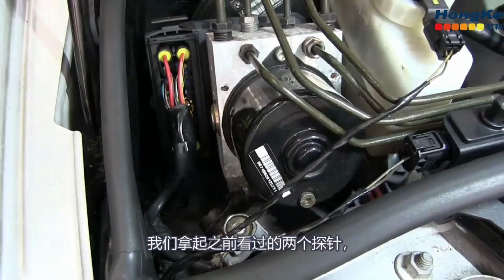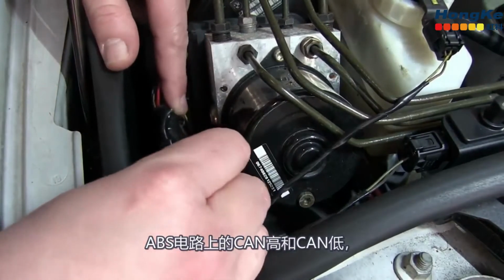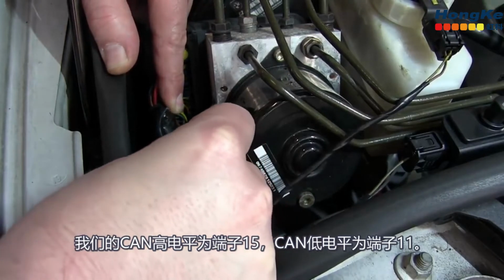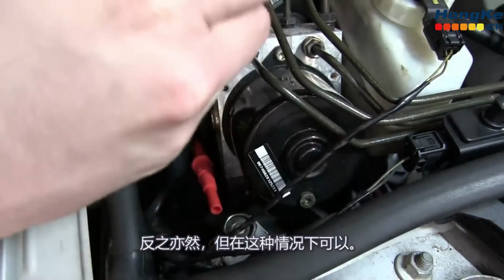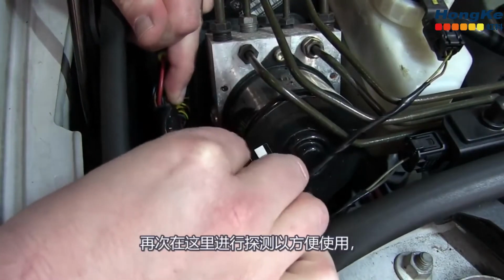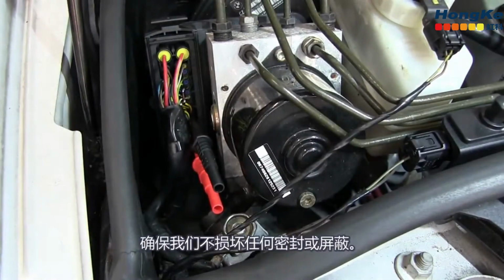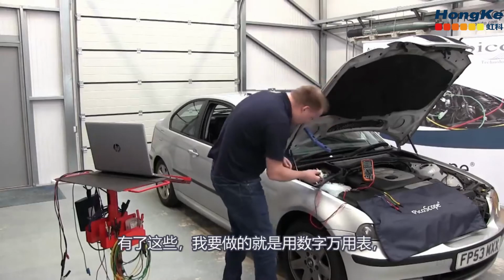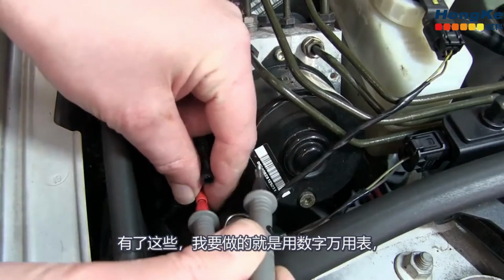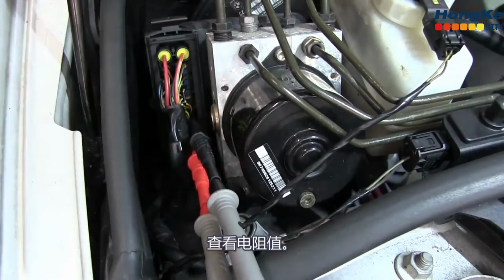So we take the 2 pins that we looked at before, the CAN high and low lines on the ABS circuit. So we've got CAN high on 15, CAN low on 11. Might be vice versa, but that's okay in this case. And again, back probing just for convenience here, making sure we're not damaging any seals or shielding. And with those in place, all I need to do is get our digital multimeter and look at the resistance.